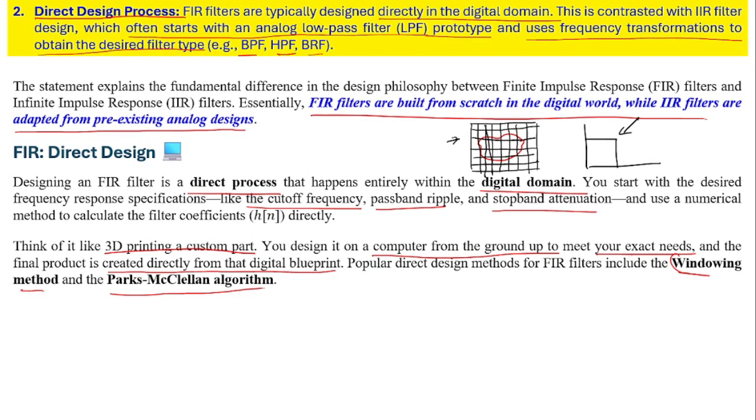So since they are not playing any role, we have to place the zeros in such a way that we are trying to emulate this brick response, because this is the ideal response. Ideal responses are also regarded as the brick response because they appear completely rectangular in shape. But in practical consideration this does not happen.